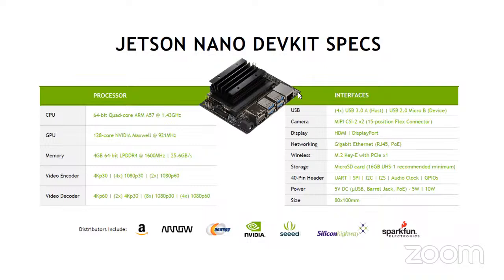And this one here is for power. So we have 2 options here for power. Either you can use this barrel connector. This barrel connector is for connecting a 5-volt power supply. You can use a normal power adapter, and using the power adapter you can easily connect the power supply. Also you can connect this to your system, and you can get a serial interface.